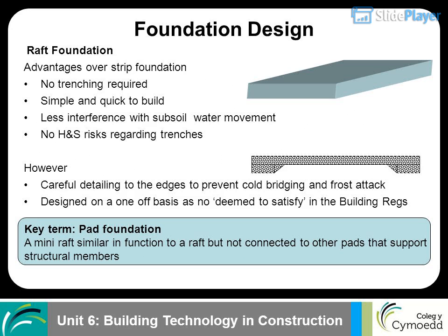Foundation design: raft foundation advantages over strip foundation. No trenching required. Simple and quick to build. Less interference with subsoil water movement. No H&S risks regarding trenches. However, careful detailing to the edges is needed to prevent cold bridging and frost attack. Designed on a one-off basis as there is no deemed to satisfy in the building regs.